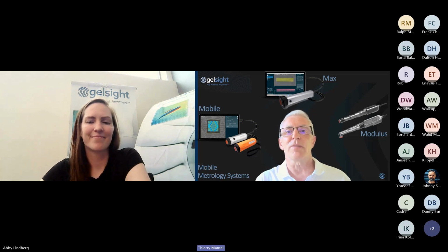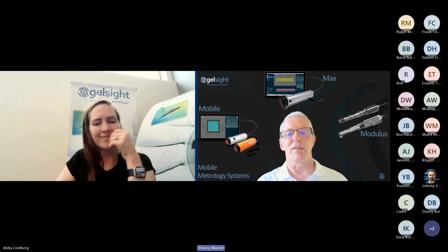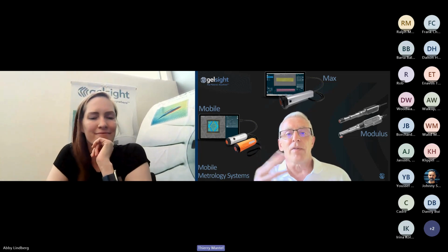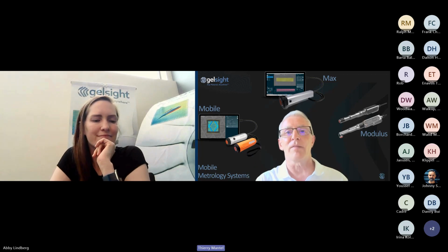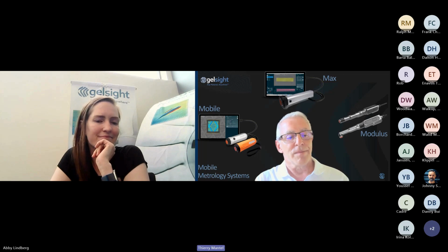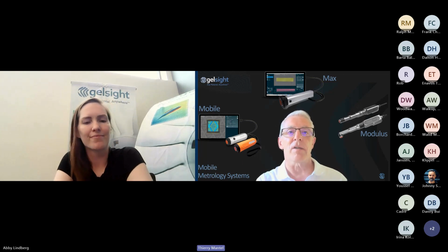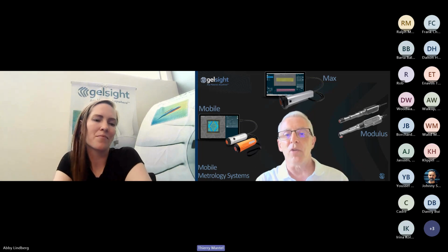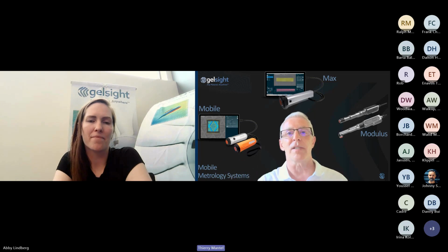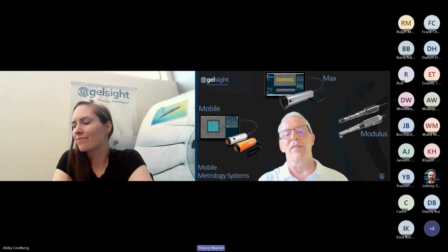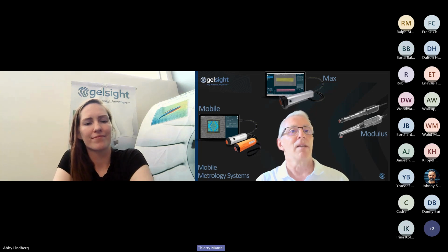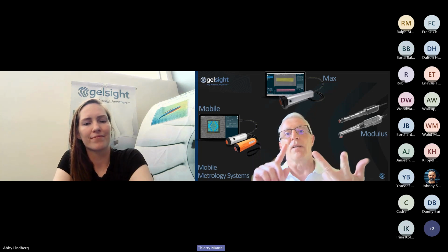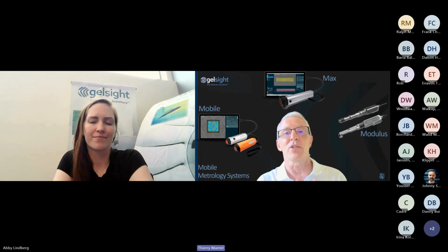The machine learning approach brings numerous opportunities to replace fastidious and subjective inspection. The first we have in mind, we talk about that with Abby many times, is to apply this type of model for the inspection of shot peening surfaces. Today, when you want to control shot peening on surfaces, you need to have an experienced inspector who examines visually the surface under a binocular and evaluates the coverage of the shot peening. This is fastidious. This is subjective. It's human dependent. You don't have a choice, and it's also tiring for the person who is doing that,